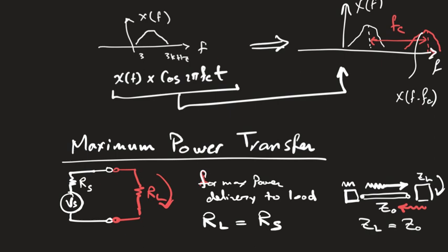And the system is going to be permanently damaged, because most of those components are very sensitive to reflected power and heat dissipation. They get dissipated where they should not, right? So you end up with a permanent damage to the system. So it's not only that you lose efficiency, but you end up with your system no longer working, okay?